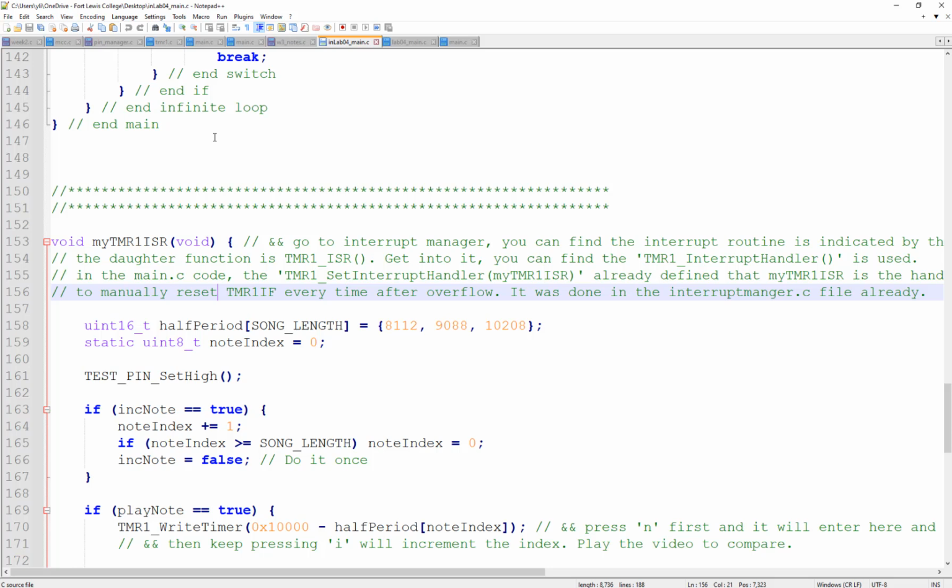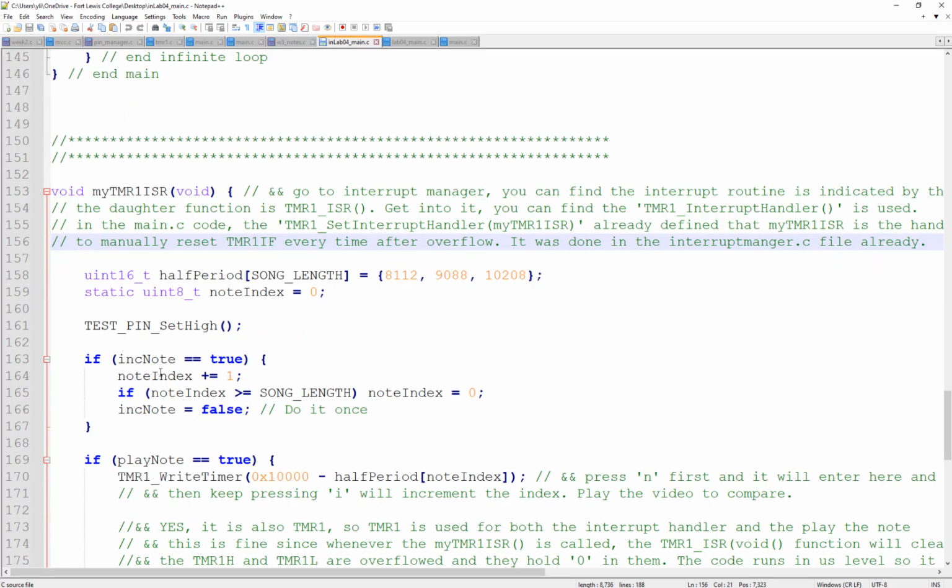After a while, the flag is 1, it detects the interrupt, goes to the interrupt routine again, and runs it. How long does it take? 4.1 milliseconds. Does that make sense? So the main file is running, and can run several times depending on what you have in the main file. Every 4.1 milliseconds, it jumps to the interrupt routine and runs whatever is inside. However, since we know that timer 1 has been used, you write something to timer 1 to play the note.